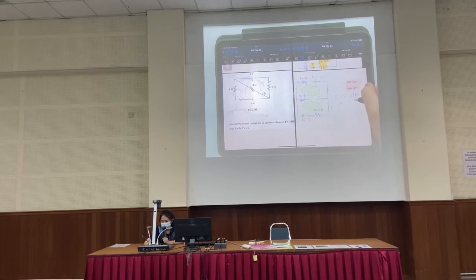And now we are going to look at the resistors. The direction of the current is to the right, and the direction of the loop is to the right too. Therefore, it will be a positive I1 times resistance 1. And we have the second resistor here.